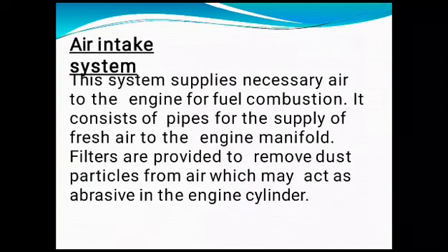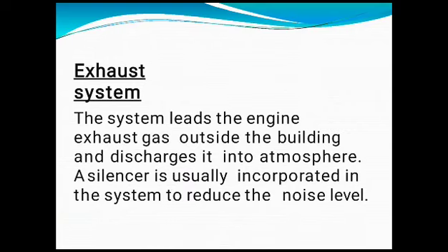Air intake system. This system supplies the necessary air to the engine for fuel combustion. It consists of pipes for the supply of fresh air to the engine manifold. Filters are provided to remove dust particles from the air, which may act as an abrasive in the engine cylinder. The exhaust system leads the engine exhaust gas outside the building and discharges it into the atmosphere. A silencer is usually incorporated in the system to reduce the noise level.